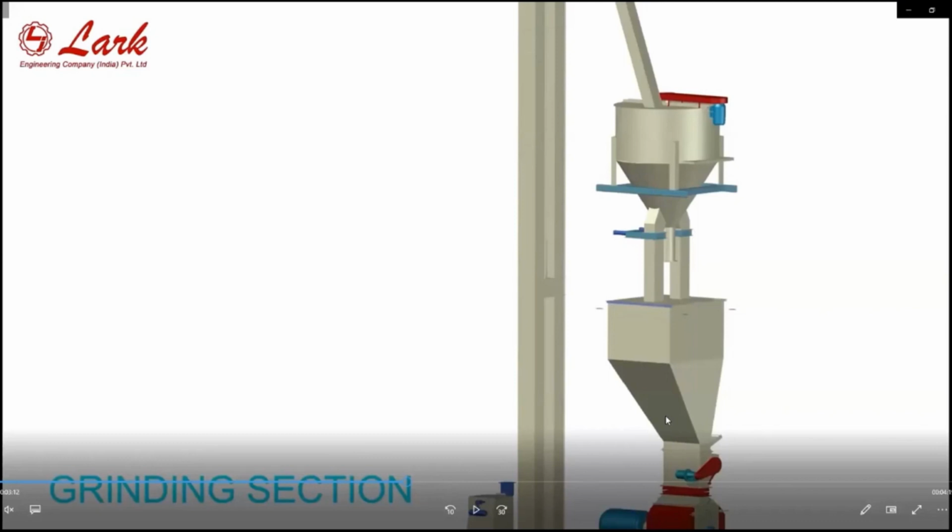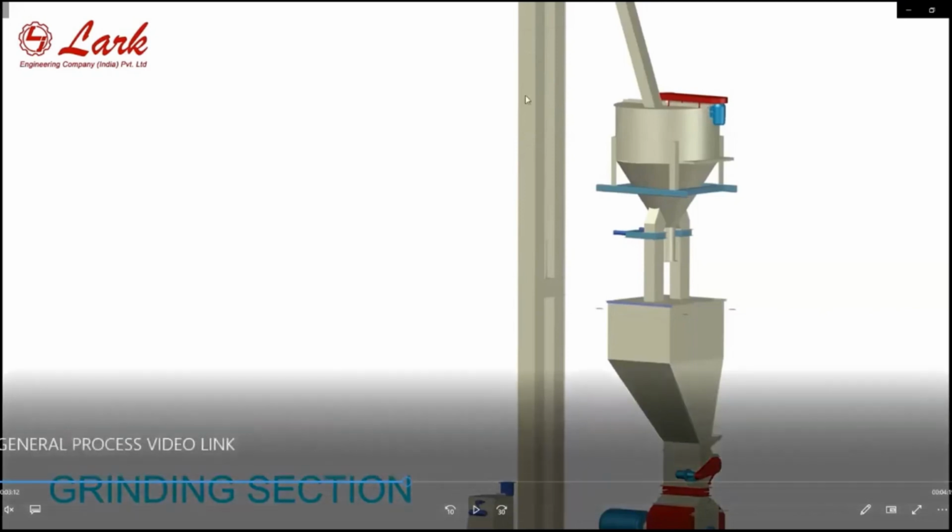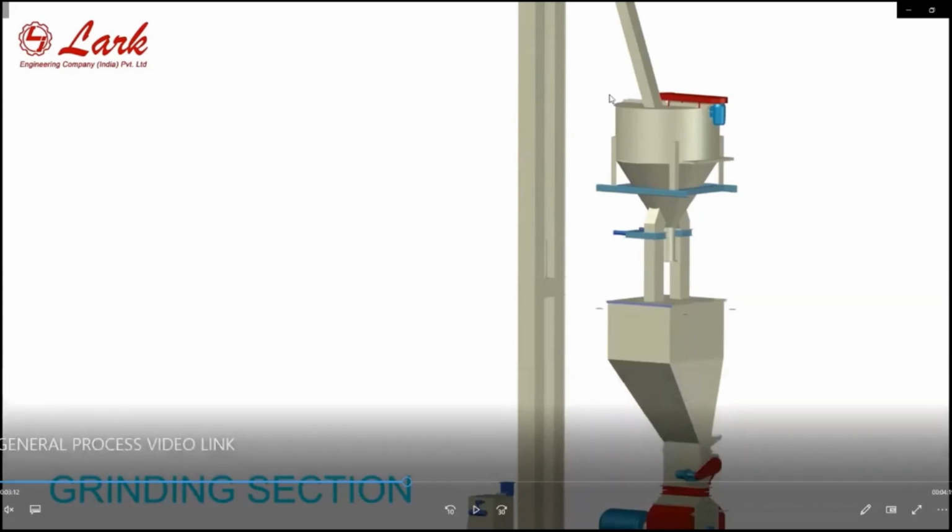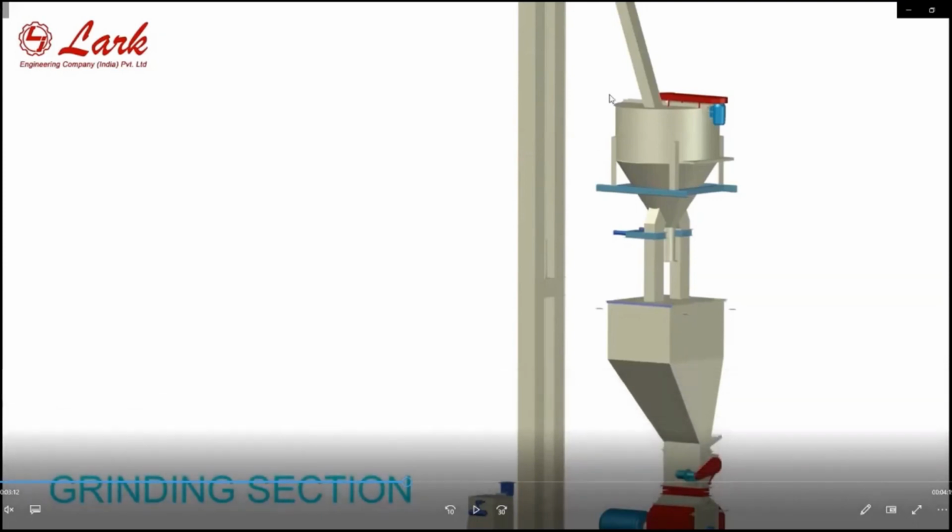So to get better grinding of the fibers also, we do pre-mixing before the grinding process for just 2 minutes. This is a conventional vertical mixer with some customized changes, placed over the hammer mill bin, that mixes the fiber and the grain equally before going to the grinding.